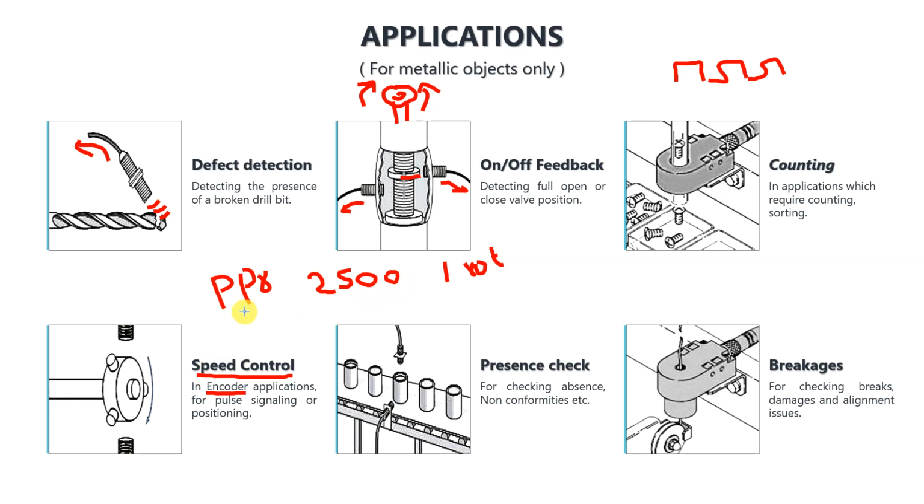However, these are also expensive, and what you can do as a cheap alternative is that you connect the motor shaft with a gear assembly or something with a protrusion on one end, and you mount an inductive proximity sensor at the one end. You adjust the sensitivity of the sensor in such a way that only the teeth get recognized, only the teeth enter the magnetic field. So what I'm trying to say is that within this particular assembly, there are three teeth, right? So there must be three pulses per revolution, right?